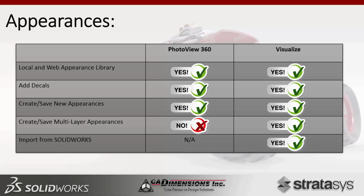Both can add decals, so that is the same across both PhotoView and Visualize. I will mention that the decals that you apply in SolidWorks will carry over into Visualize as well, so you don't have to reapply them, but both do have the capability to add them in each respective software as well. Both will allow you to create and save appearances. So if you get something just right, it's just the right color and all the specs are exactly the way you like it, you can save that out in both scenarios.